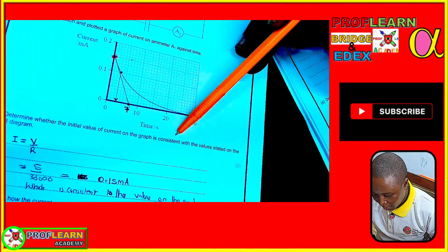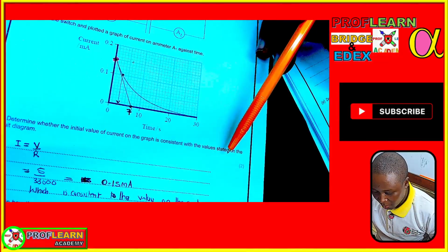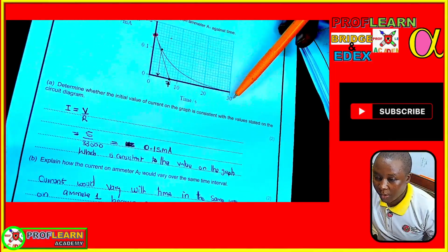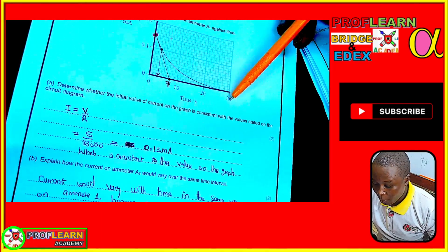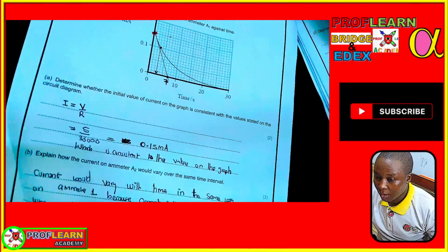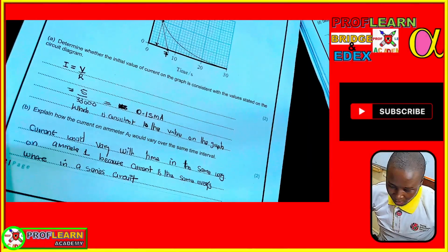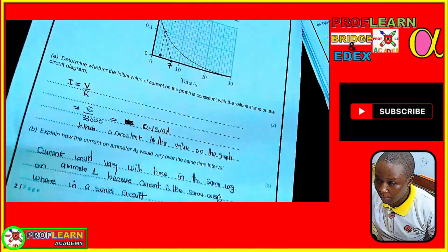We are told to determine whether the initial value of the current on the graph is consistent with the value on the diagram. So in this particular part, we are going to use the formula current is equal to V over R, where V is the voltage, which is 0.5, and the resistance that we have here is 33 kilo ohms. So at that point, we are supposed to work it out so that we can check the value.